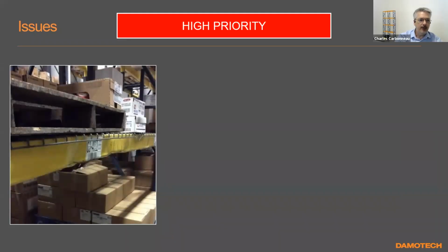Another high priority here, a damaged beam. It's rippled. Perhaps, because it's damaged from the bottom mostly, it probably has enough capacity. But again, it goes back to, yeah, but do I really know? No, I don't really know. And this one, by the way, was doing like a vertical arch. So you reload it. The worst that can happen is to have it come down.